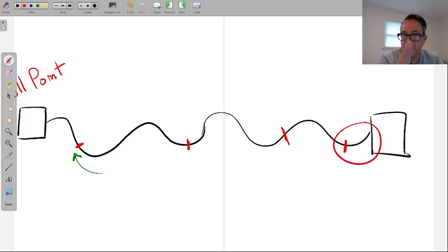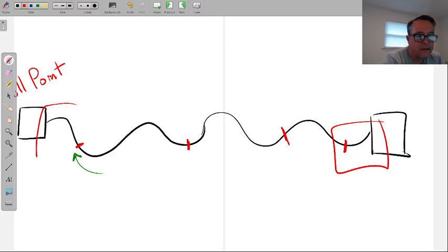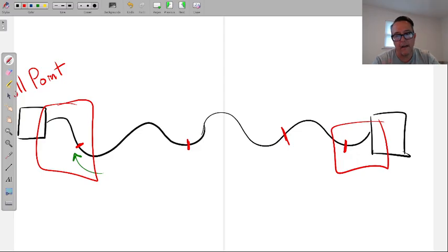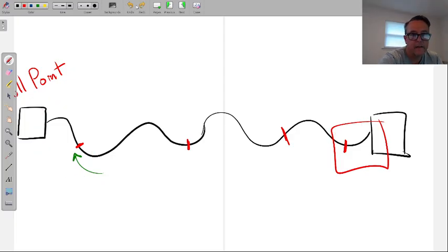And this one is a tough one, because what if I've run it and I'm at 18 inches from the box? No, you still have to put another one here. So still have to be within 12 of this box here, and within 12 of that box there, even if your other supports are landing pretty close to this one. Still have to consider that, and I have seen them fail inspections for that. They are sticklers for supporting the conduits.